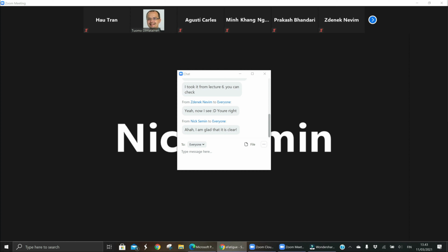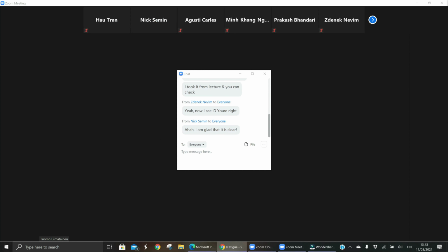Tilma, do we use von Mises for nominal loading stresses? You don't need to use von Mises, or rather it doesn't matter if you use it, because the result is the same, since you only have tensile components in the stresses. If you put them all into Mises, you will eventually get the same result as without. However, we need to calculate the mean stress. The mean stress is coming. Now you need to check the loads.